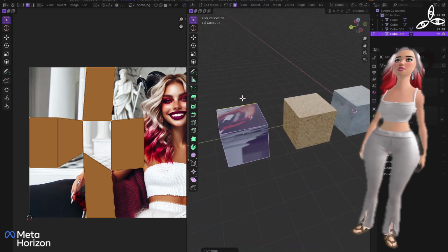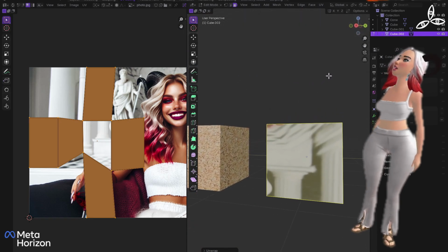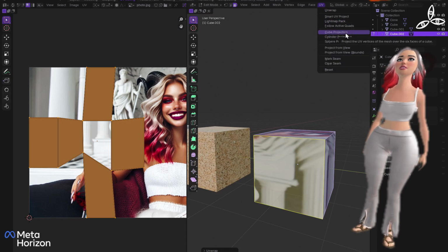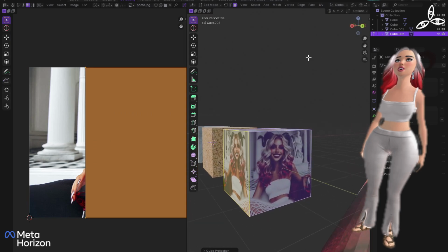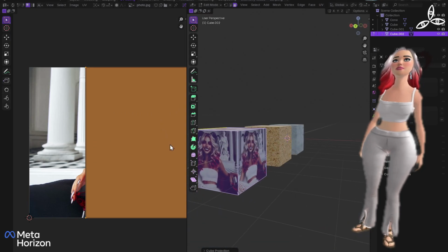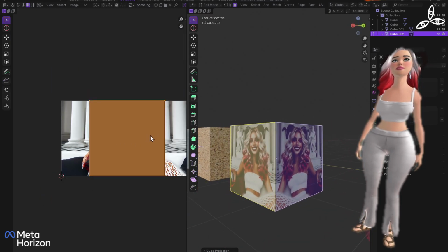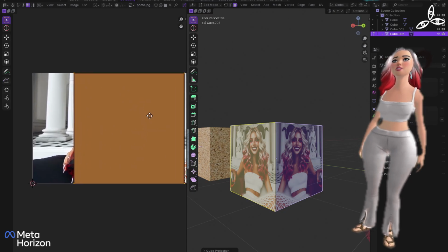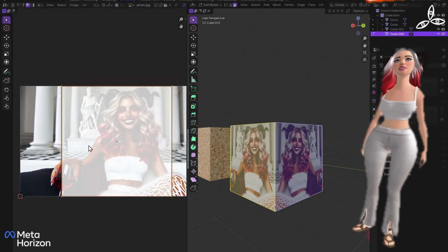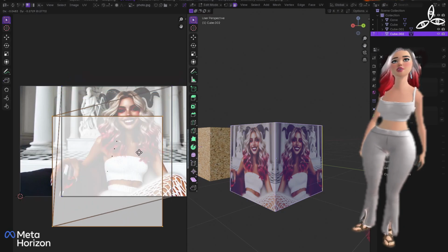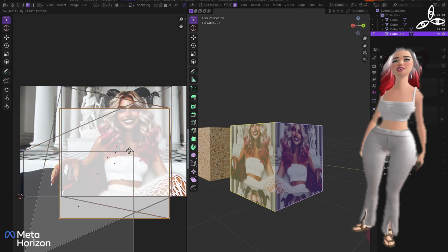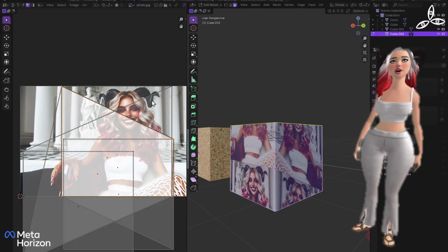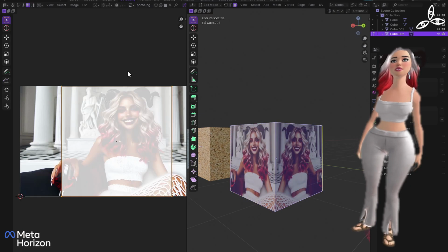So, there are no ideal ways to unwrap in Blender, depending on the object you're working with. So in this example, I might choose to use a cube projection. So let's try that. So cube projection has quite simply created a single UV map here, which is actually this. And what's happened here, and this is absolutely okay in UV maps, all of these are overlapped with each other. So if I grab one, you can actually see it's over the top of the others. And grab another again. And you're kind of seeing something else in there as well that's an important feature.